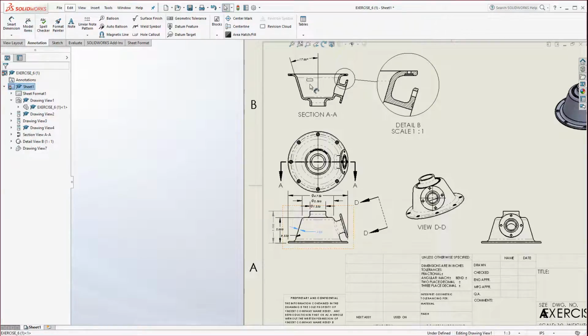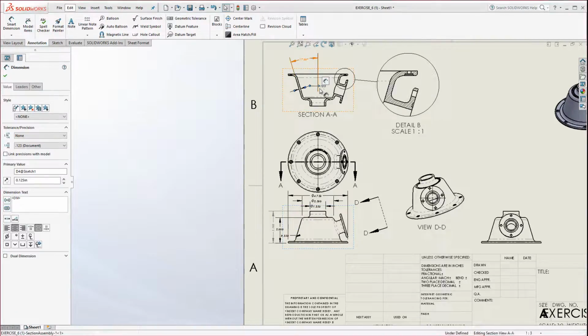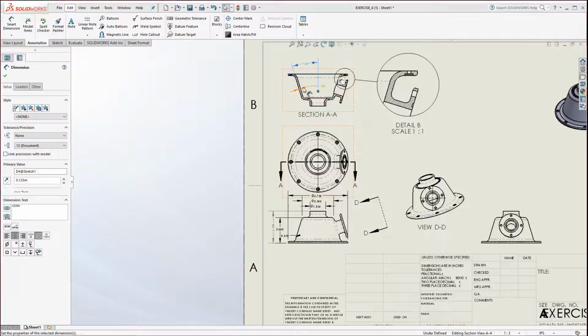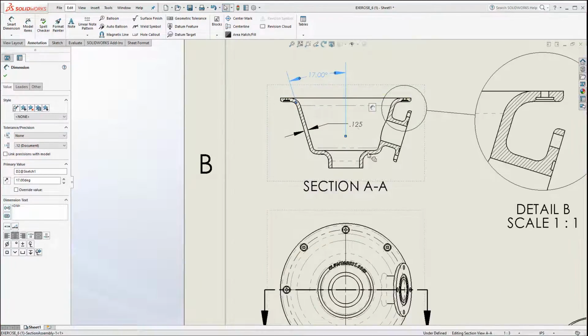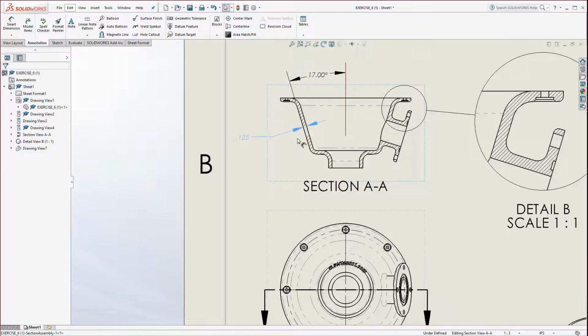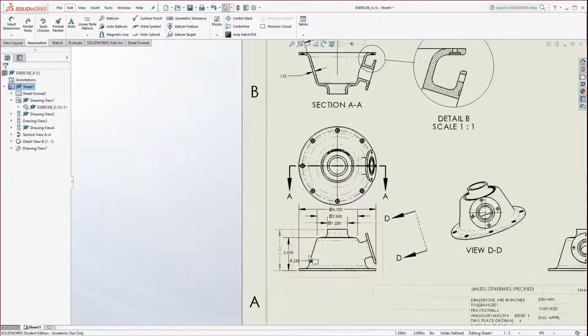If you hold the control key, it will make a duplicate copy, and you should know that that goes against rules of drafting, so you don't want duplicate dimensions typically. But if you need to, know that the control key instead of the shift key will work for you.